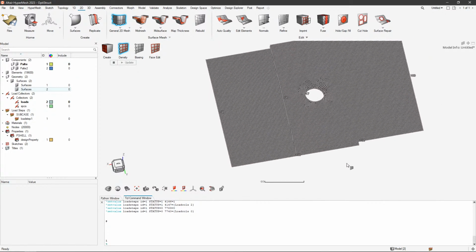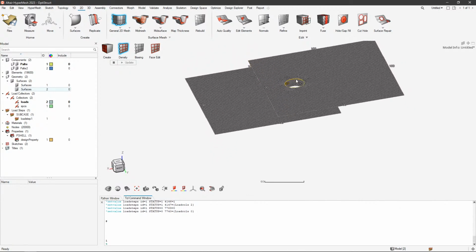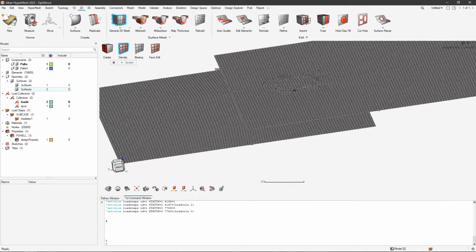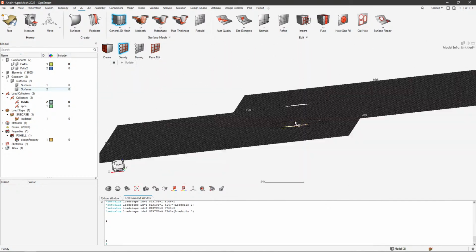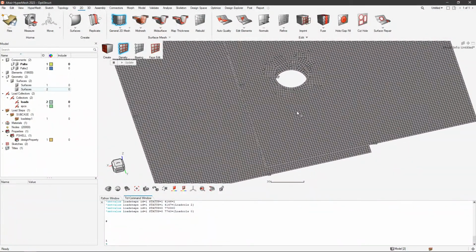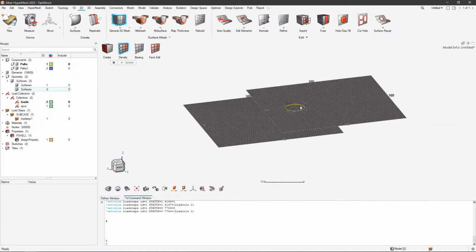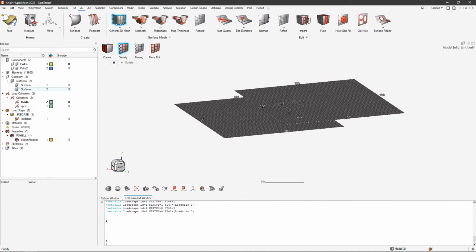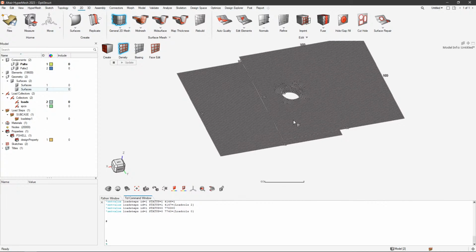Now, the next thing I will do is create a bolt connection with a rigid. To be honest, the correct way would be to model a rigid here and a rigid down here, and then connect those two with a bolt, because the bolt then has a stiffness. But I will not do that. Maybe in a future instance I will. For now, just the most simple approach you could think of: a rigid here in the middle. I don't constrain anything on there, it's just to connect it.